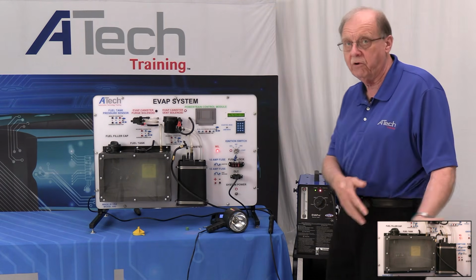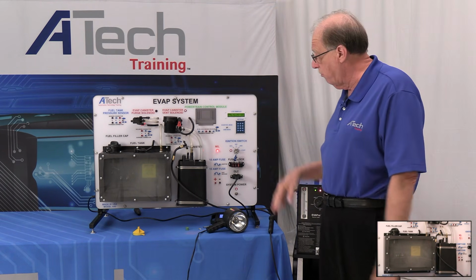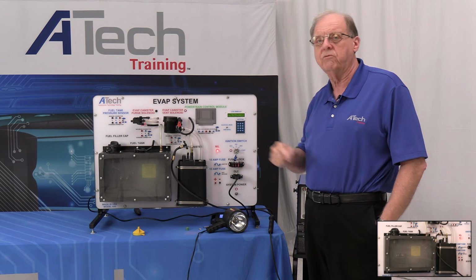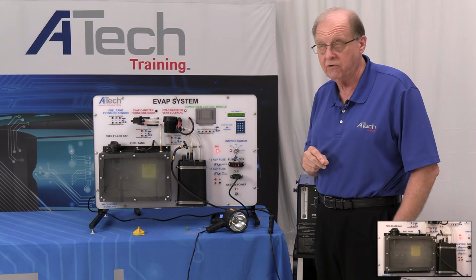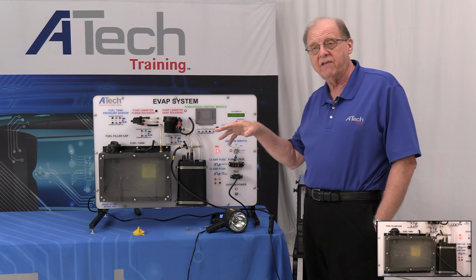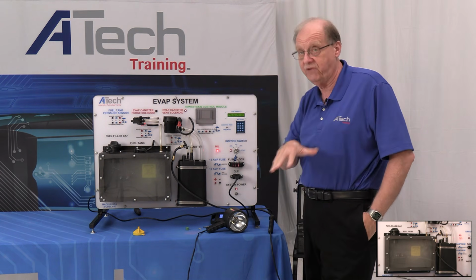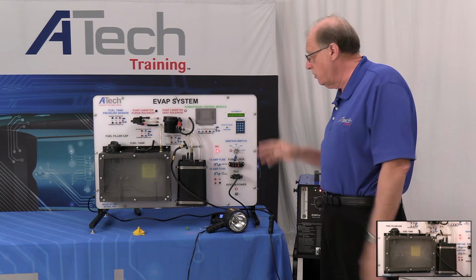When we talked earlier, it's a big plumbing system on it. So if we do this process, you're going to follow the lines down, any connectors especially. Follow the leak down the lines all the way to the tank and the tank itself. The tank itself can leak. So you want to follow it down, use your light.